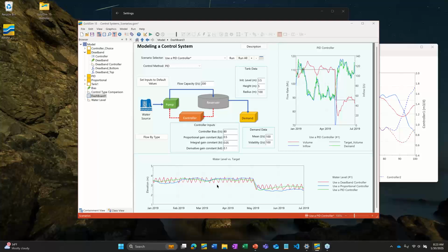You have a proportional gain constant that you essentially multiply by the error, how far you are away from the target, and then it just applies that value. So the further you drop below or go above your target, the more your controller will respond. If you give it a higher gain constant, then it will respond with higher magnitude relative to the error from your target.